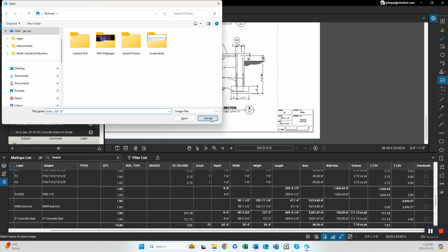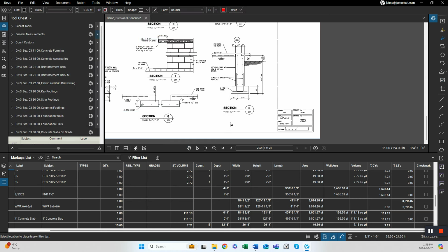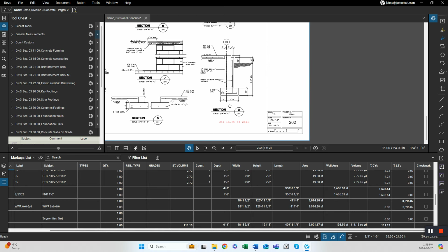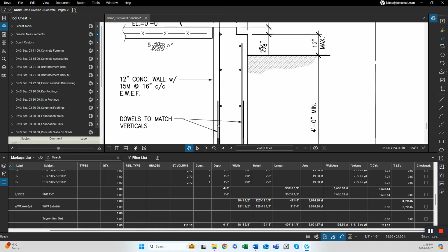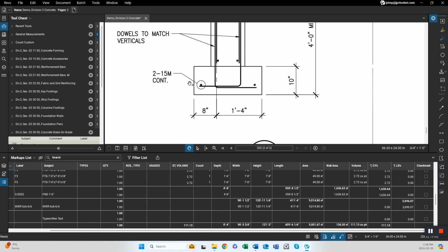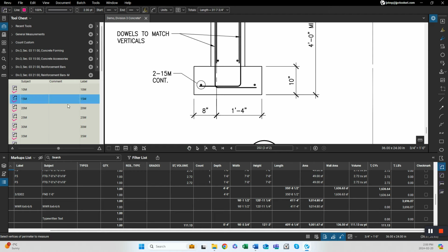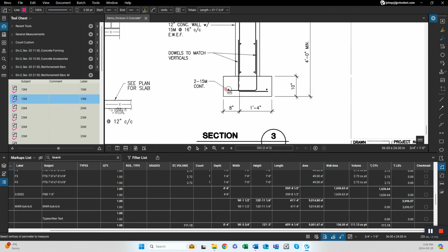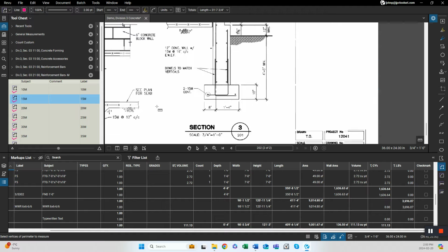Oh, sorry there. So this is 351 linear feet of wall that we have, and the footing also. So to do this, what I like to do is, okay, let's look at our rebar and our footing. So we're using 15M. So if I go in my metric, my 15M, so what I'm gonna do, we know that we have two rows of rebar in our footings.